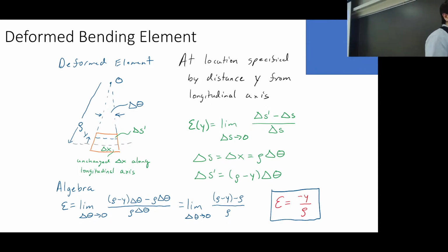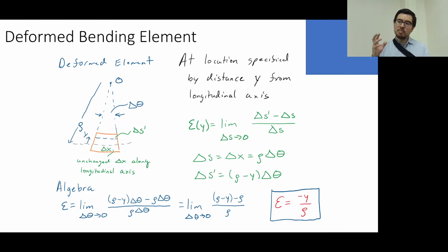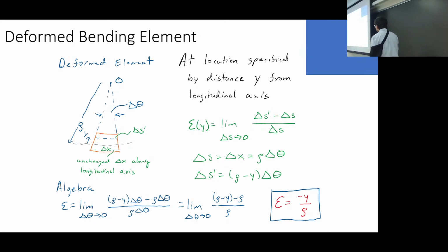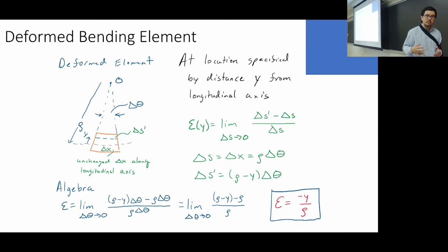And you can now begin to predict. Okay, and why is it 0? So the way you can say it's 0, okay, is because it's at y equals 0. That's where the strain is going to be equal to 0. And if the strain is equal to 0, right, sigma equals E epsilon, this is actually a form of normal stress, right? So that's going to be 0 stress. 0 strain, 0 stress. At least due to bending.